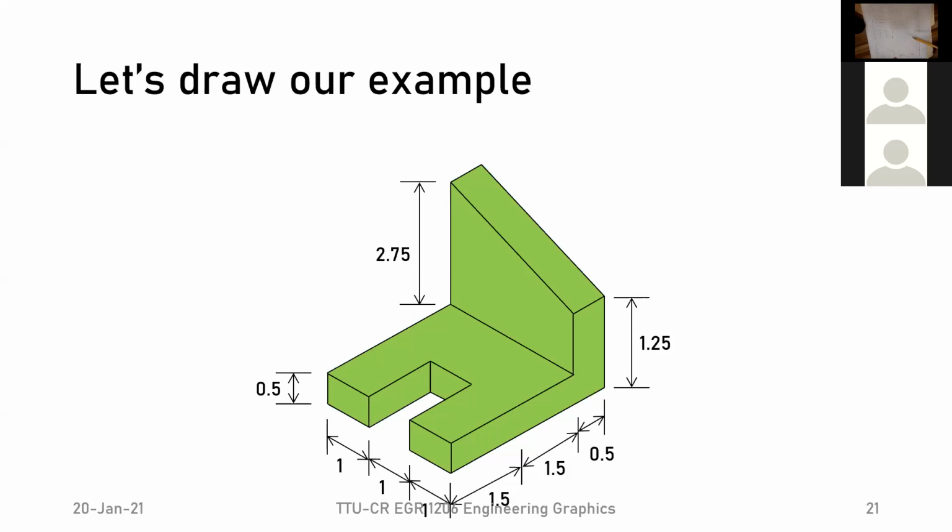But there's a convention that says that we want to have these 3 views together, right? That the front view is in the bottom left, the top is above, and the right one is to the right. That convention is always there. But the relationship between the top one and the right one is not necessary.